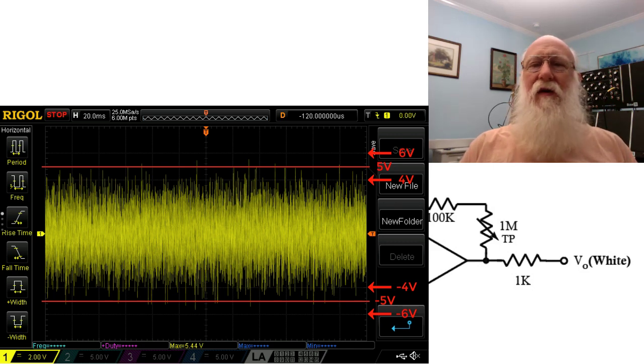As shown here, an occasional peak hits around 6 volts, but not too many peaks exceed about 5. You can argue a lot about whether you ought to try to reduce that so that none of the peaks go above 5 volts, but there's no way you're going to get an exact plus and minus 5 volt signal just due to the nature of noise itself.